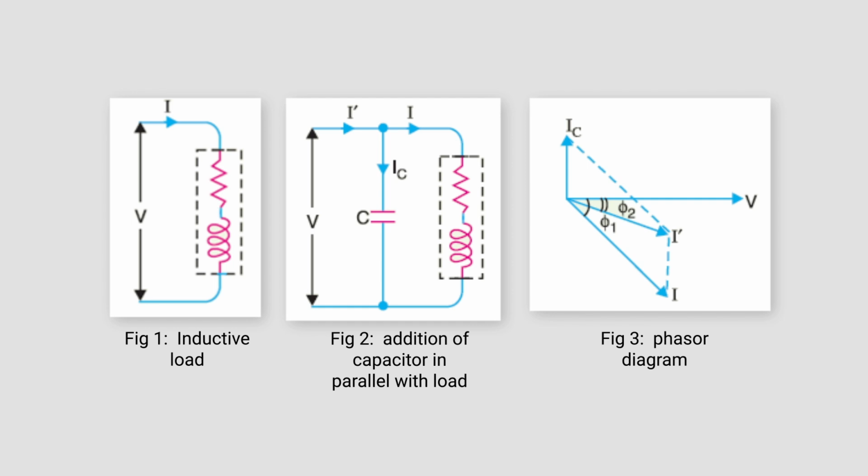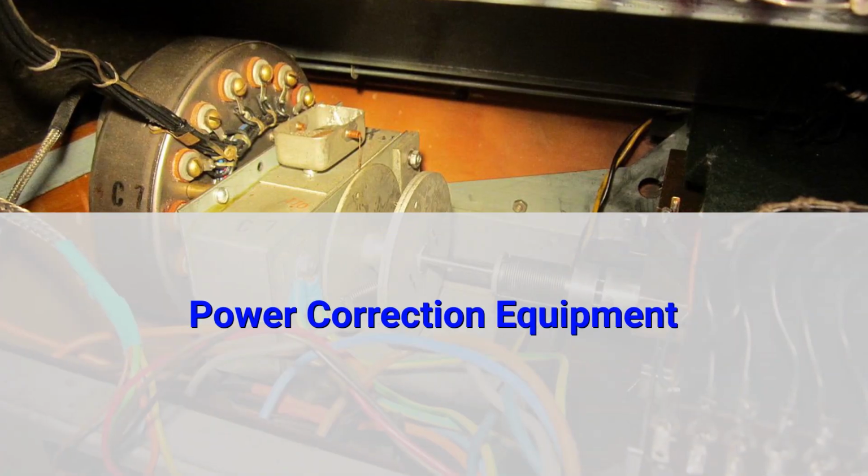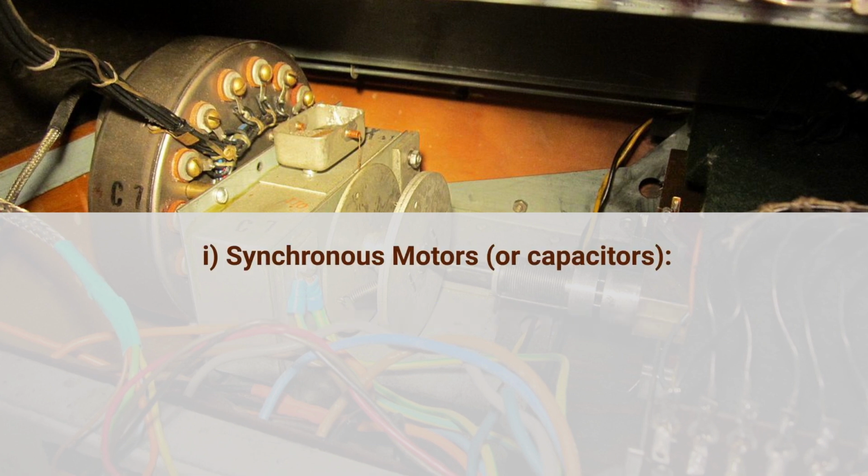this inductive load. Now we have discussed how the power factor can be improved by simply inserting the capacitor in parallel with this RL circuit, or you can say inductive load. There is another method by which you can also improve the power factor. So the first method is the synchronous motor. If you introduce the synchronous motor, you can also improve the power factor.